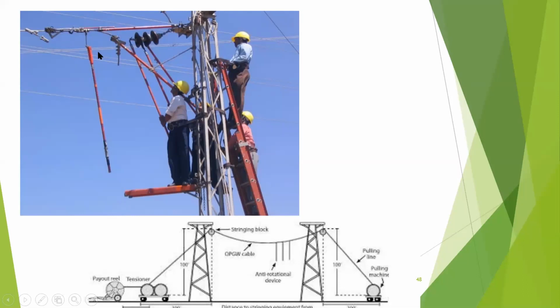They are doing a hotline operation, and a come along clamp is over here, and with a hot link stick they are trying to tension the conductor a little.